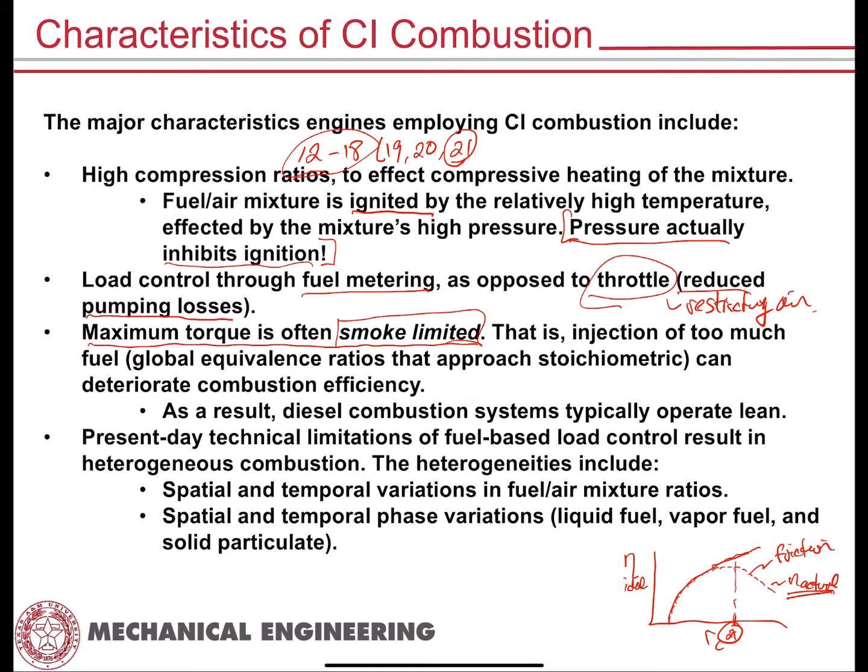And the bulk of your particulate matter is soot, and that's basically what smoke is, okay? So as you go to higher and higher fueling levels at any given load condition, you're raising your in-cylinder equivalence ratio, but you're making it more and more difficult for that fuel to undergo all of its physical processes before ignition, and you end up generating higher and higher concentrations of smoke or soot.